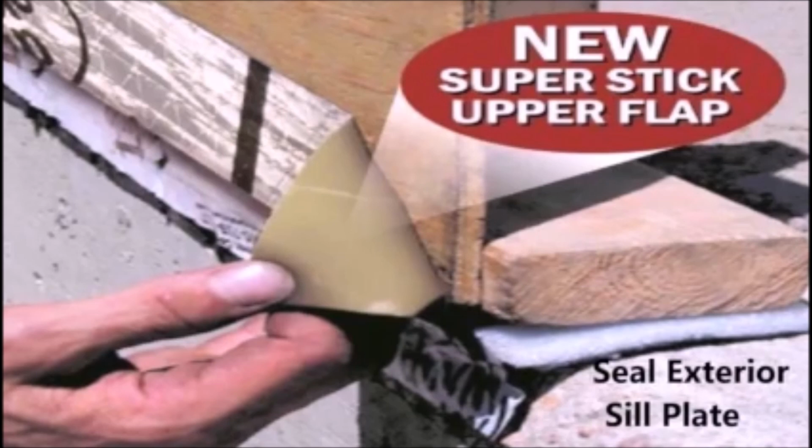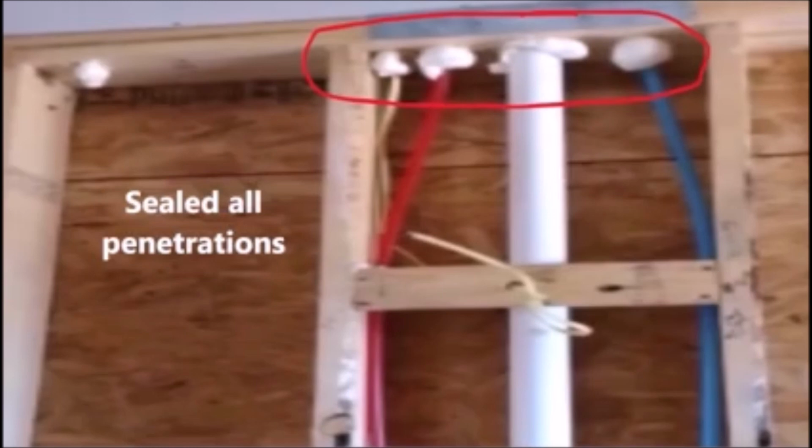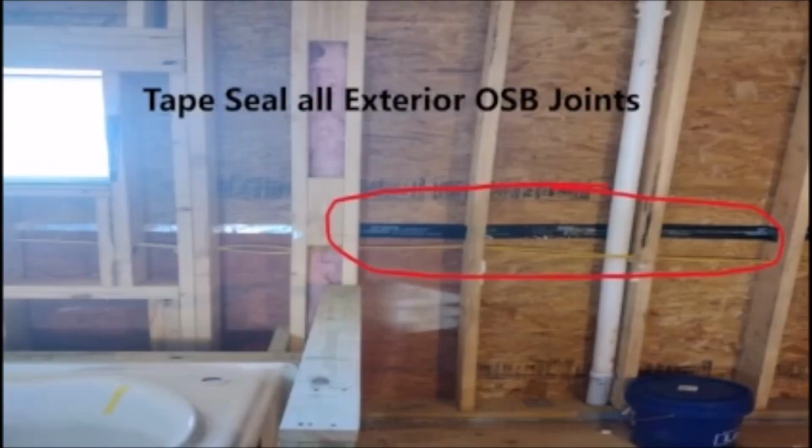On the interior of the 2x6 wall, we silicone caulked at the base plate. Then we also sealed all the penetrations from the first floor into the attic space. And the last thing that we did was tape seal all the exterior OSB joints on the exterior wall.